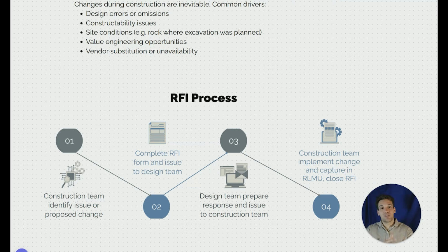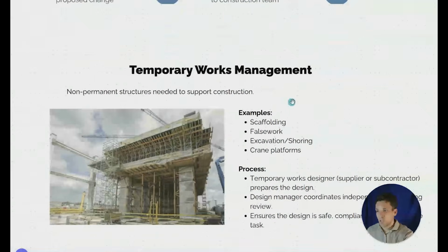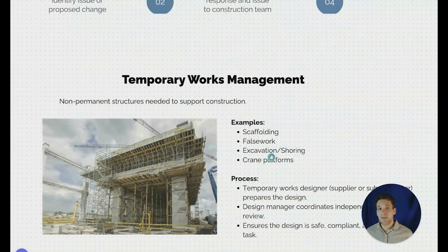So they implement the change, so they've shifted a trench a meter across. They'll then need to mark up this change on the drawings so that there's an as-built set of drawings developed showing what's actually installed.